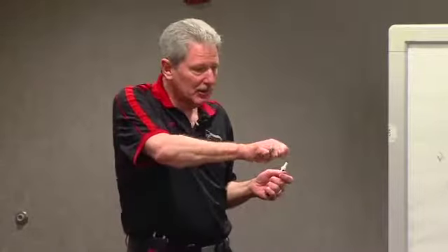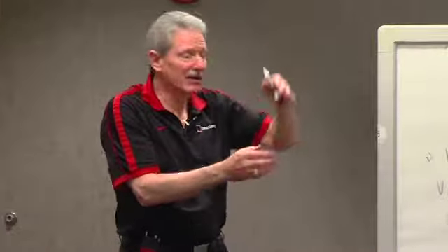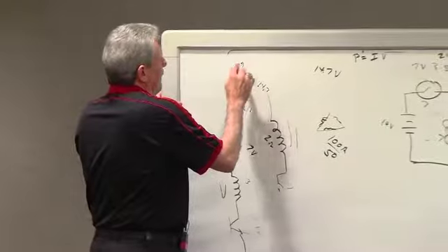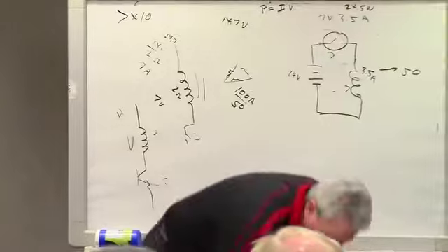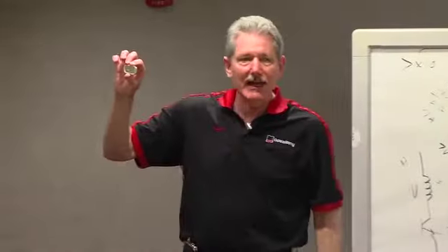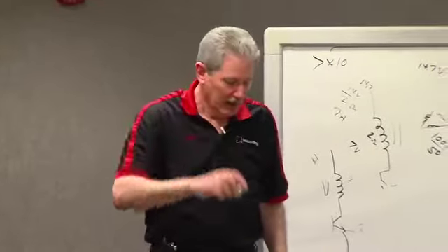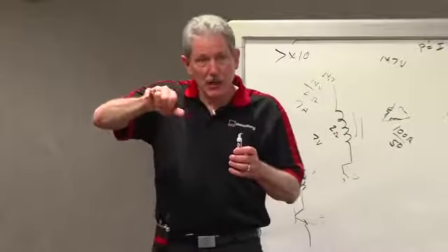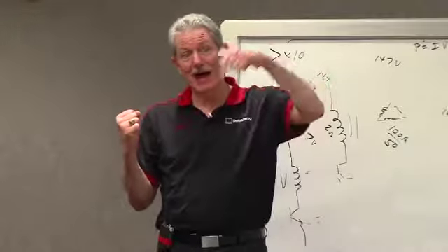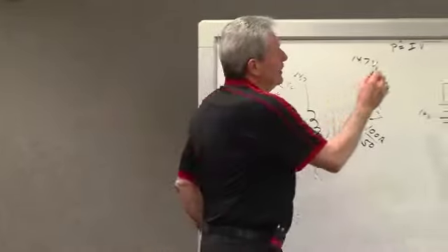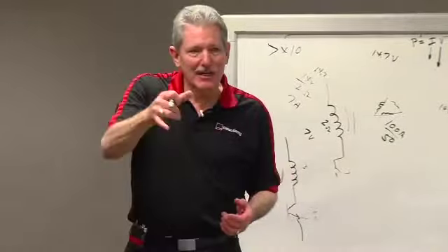The easy way to do is just to change the voltage. But when you do that, you have a really bad power dissipation, like greater than 10x. Well, we're dissipating the power on a backplate that's like that. You can't dissipate 24 watts with that small area. So the reason why we have switching is when it's open, there's no power because there's no current. When it's closed, there's low power because you have a high current but low voltage. So as long as this is small or this is small, your power's low. That's why you have the switching.